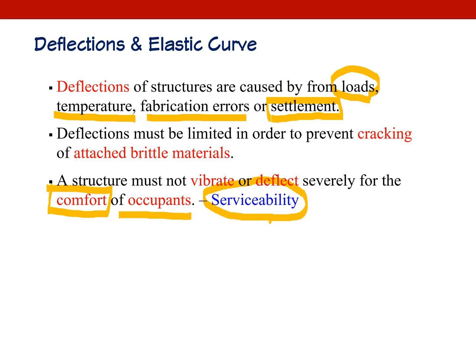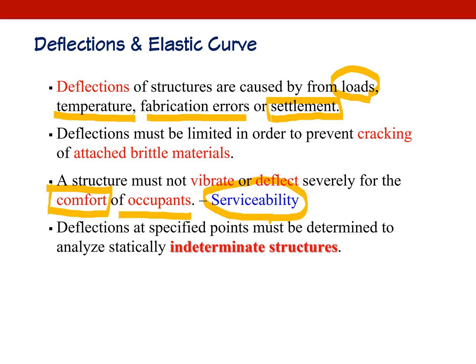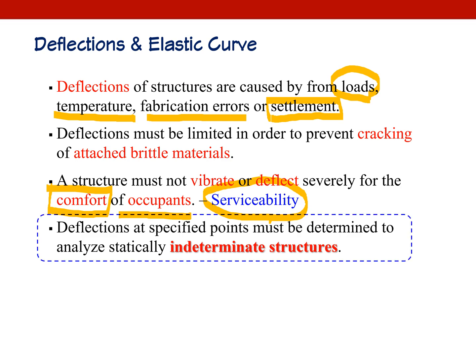So we have two issues, serviceability and strength. Most importantly, deflection is required to be calculated to analyze indeterminate structures. So this is our first step to come up with an additional exact equation using deflection for indeterminate structures.